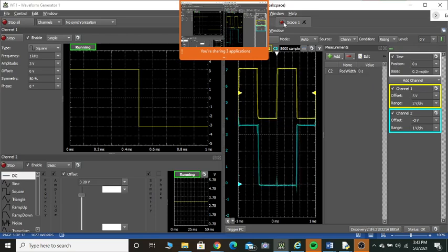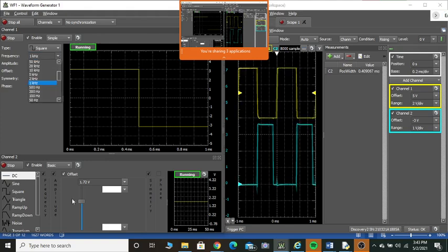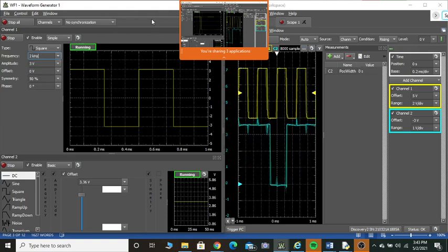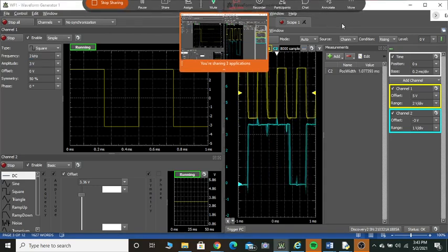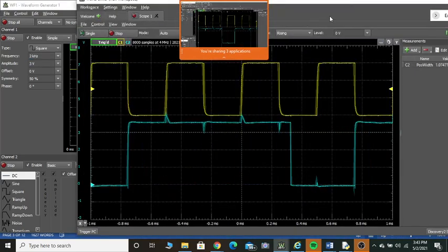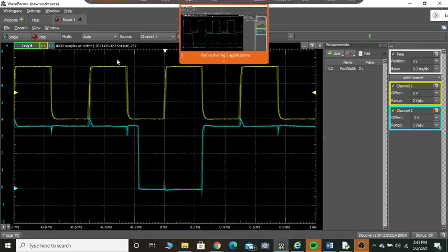Can we now see the pulse width can be modified by changing either the control voltage or the RTCT? Correct? Can we demonstrate non-retriggerability? Meaning, if I apply the trigger signal, let me make sure this is my width. Can you see this is the width now? I will increase the frequency of this to 2 kilohertz. See the change. You can clearly observe what you mean by non-retriggerability. Let me just demonstrate that. I will stop this.